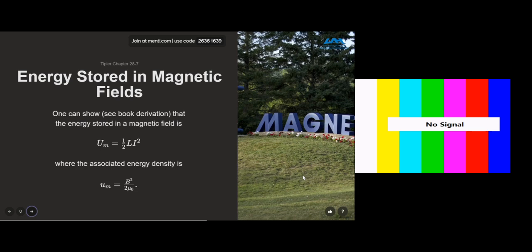Again, kinetic energy is measured as 1/2 mv squared. Here we've said that L, the inductance, is a measure of electrical inertia inside of your circuit. So we've got 1/2 times inertia, inductance, times velocity, which is the movement of charge, so current squared. So we have that the energy stored inside of an inductor is equal to 1/2 Li squared.